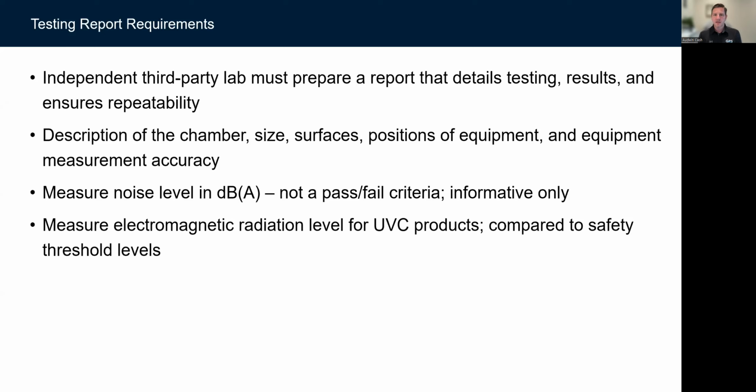I think it's really interesting. One of the things that we've heard from customers in the field is, hey, I installed these, or I brought these air cleaners into the classroom, and they're at 45, 50 dBA, they're noisy. They didn't say 45 dBA, they're just too noisy. So we unplug them, or we turn them down to low level. Well, okay, but is that HEPA filter running at low level effective at cleaning as much air as you need? I don't know. And so looking at the noise level at the performance level is helpful as an engineer to know what the likelihood is of a happy customer when it's installed, which I think is pretty cool.